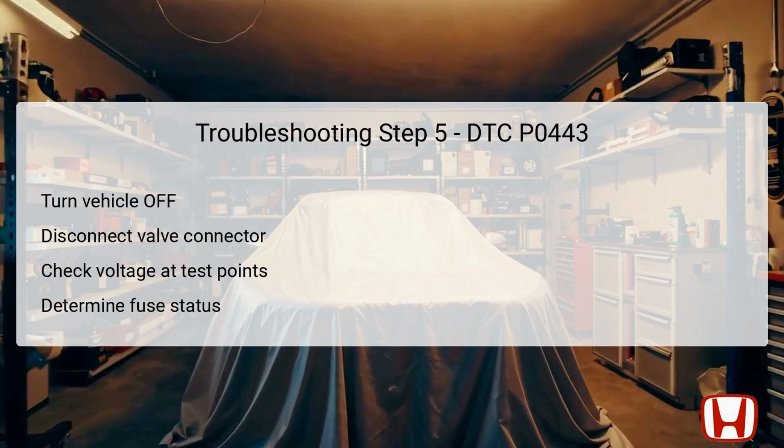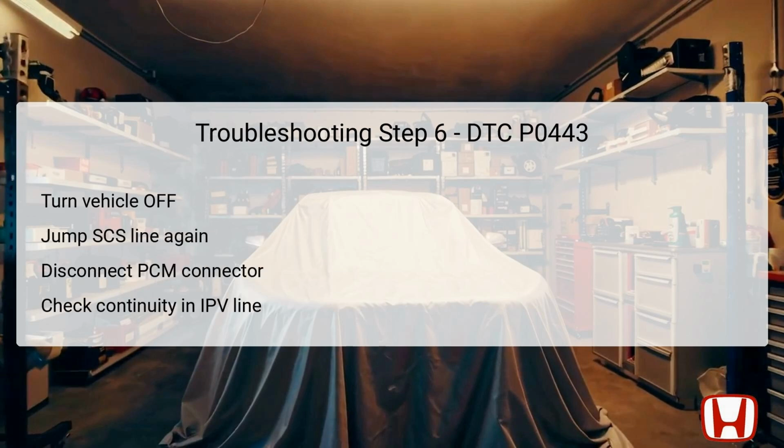If battery voltage is detected, it indicates that the IGPS ignition power supply wire is functioning as expected, allowing you to progress to further diagnostics. However, should voltage be absent, investigate the number A11 5A fuse located in the underhood fuse relay box for any signs of being blown. If the fuse is compromised, it must be replaced, and a potential short to ground checked in its circuit. If it's intact, then an open in the IGPS wire between the purge valve and the fuse must be inspected.